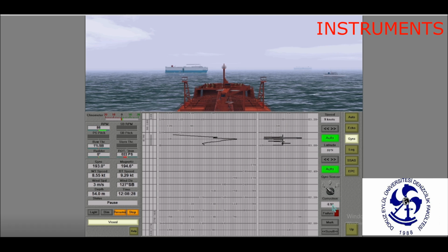The left-hand part of the course recorder chart: a broken line will be drawn which allows determining the quarter in which the course should be read off in the central part of the course recorder chart. In the right-hand part, the position of the rudder blade is drawn. Press the mark button to draw a horizontal line for the current time on the chart.